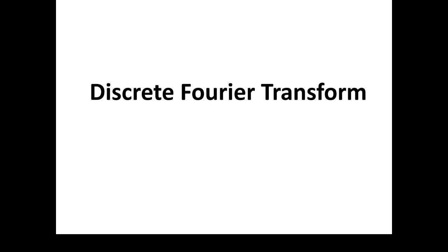Now the problem I have already told you about: in the discrete time Fourier transform, the inverse discrete time Fourier transform implements integration, which is a continuous operation. Due to this reason, the transform could not be implemented in digital systems. Due to that reason, the discrete Fourier transform was then developed.